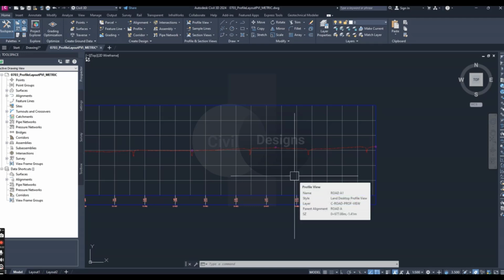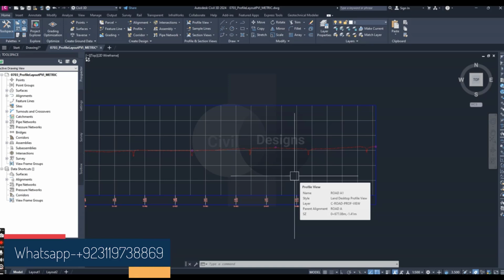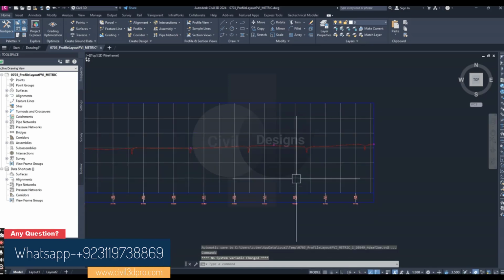The sample surface information contained in a surface profile is normally dynamic with the surface definitions. Moving into the design stage, we will see how these improvements are a benefit as we look at the nature of creating design profiles. By working with layout profiles as a collection of segments that understand their relationships with each other, we will realize the power of the AutoCAD Civil 3D software as a design tool in addition to being a drafting tool. So we can create layout profiles in two basic ways.